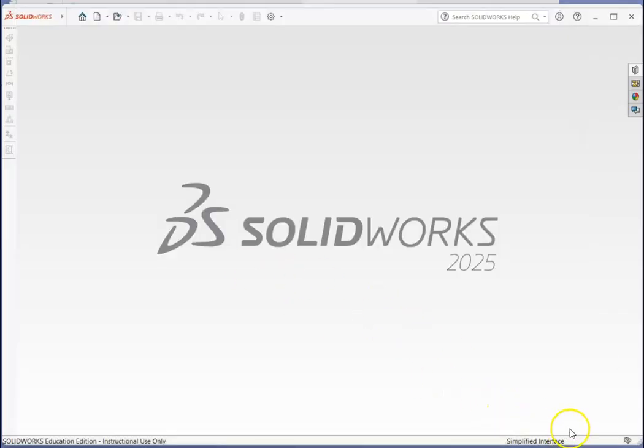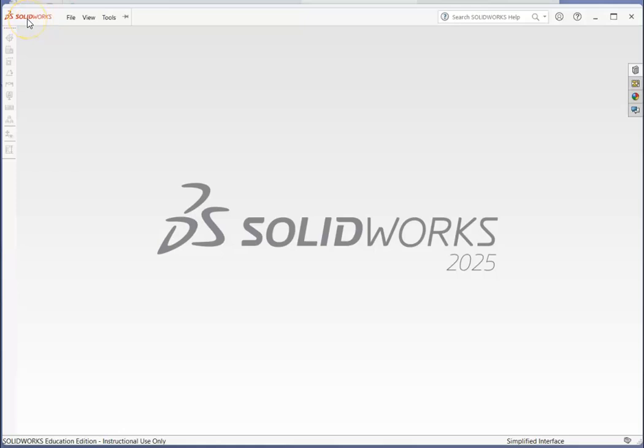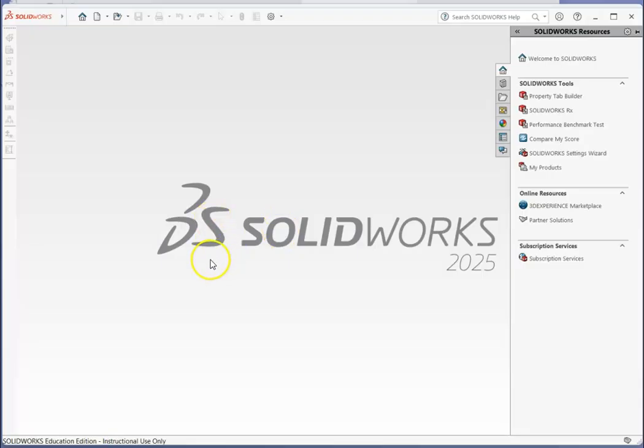The first thing I think we should do is turn off the simplified interface. You know you have the simplified interface on if you look in the lower right hand corner and you see where it says simplified interface. Go up to the top left hand side, click where it says SolidWorks, move your mouse over to View, go down and uncheck Simplified, and it'll be gone.